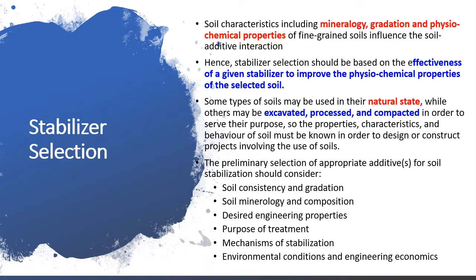The preliminary selection of appropriate additives for soil stabilization should consider soil consistency and gradation, soil mineralogy and composition, desired engineering properties, purpose of treatment, mechanism of stabilization, and last but not least, environmental conditions and engineering economics.